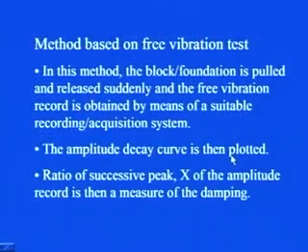Then the amplitude decay curve is plotted. As you know, some amount of damping is always there in any system, be it a forced vibration system or a free vibration system. In a free vibration system, the system vibrates under the influence of the forces which are inherent in it. There is no external exciting force.